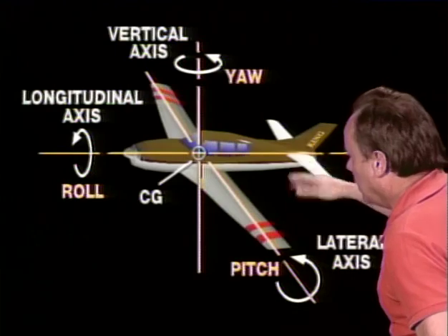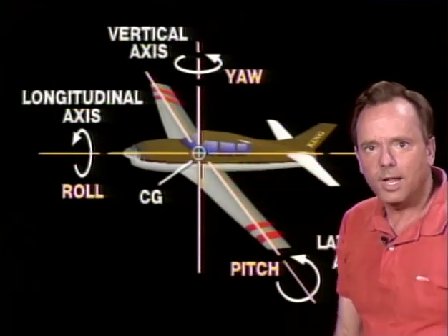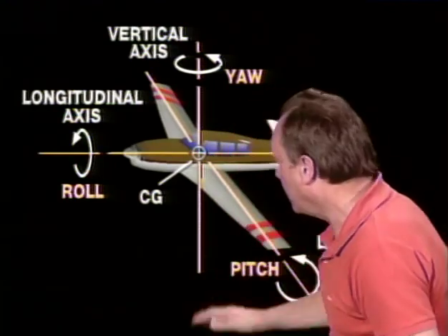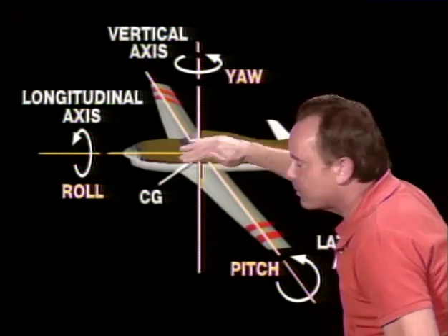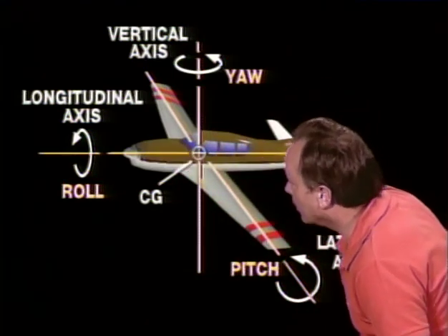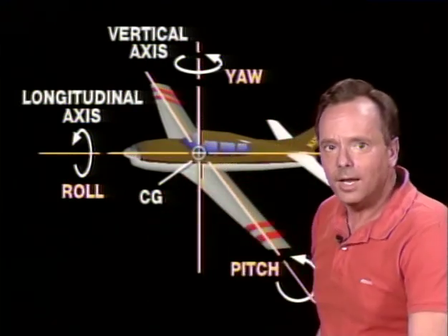So the lateral axis is what the airplane pitches about, and that's what improper rigging of the elevator trim tab system would affect: the balance of the airplane about its lateral axis. Now, if they talked about along the longitudinal axis, they'd be talking about along this line, but it's about the lateral axis. Now let's talk about wing twist and washing in and out of wings.